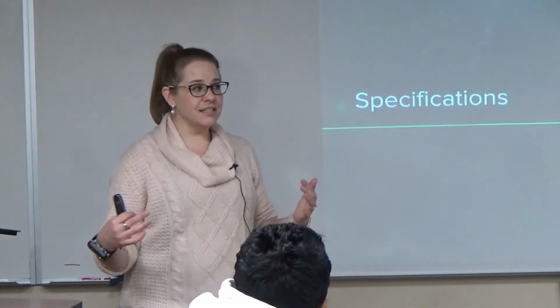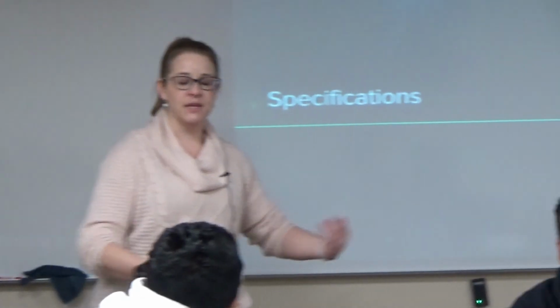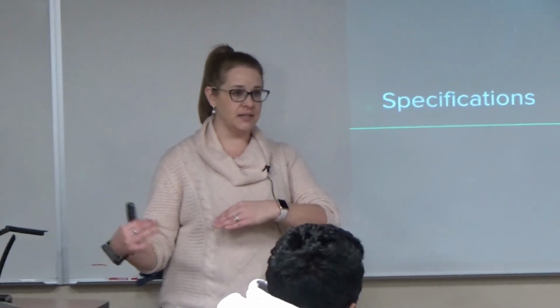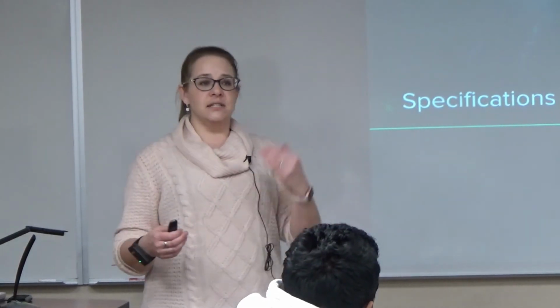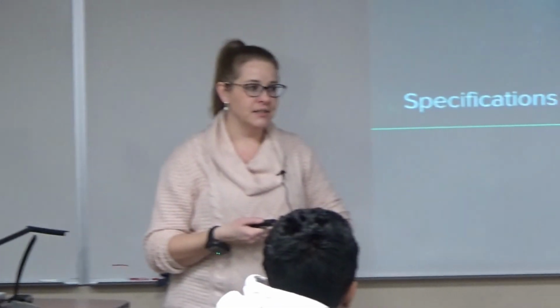Then finally, we're going to talk about your specifications. This is where I feel an engineer differs from a different type of designer, because we like things to be quantitative. This is where we're developing those needs and requirements into something quantitative. The reason I like this in particular is that it gives us a quantitative way to see how we did in the end. So if you say it needs to weigh 10 pounds or less, when you've developed it, you can weigh it and compare it.